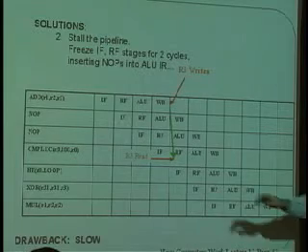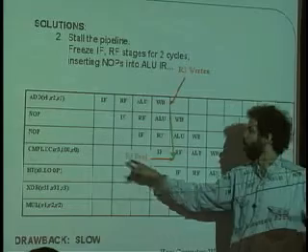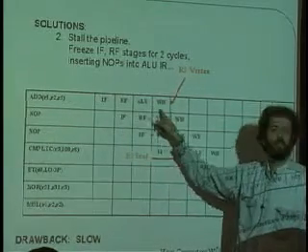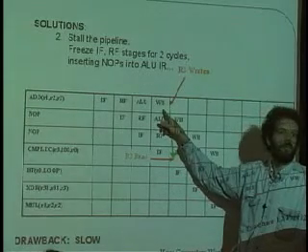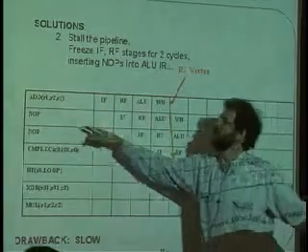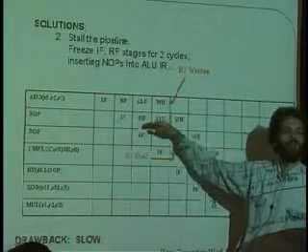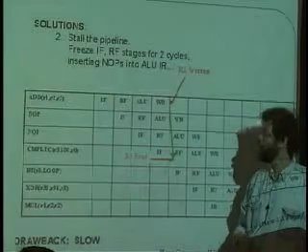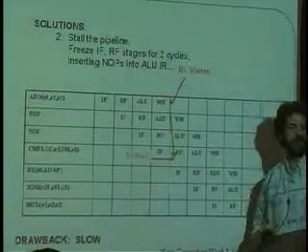And when it fetches an instruction like this compare less than or equal that wants a dance with a register that is destined to be written later, what it says is, well, you just got to wait, buddy. And it stalls the pipeline by inserting no ops, or no operation, into the pipeline. In this case, you need 2 of them, and it basically stalls the machine for 2 clock cycles and then allows the compare less than to go through.